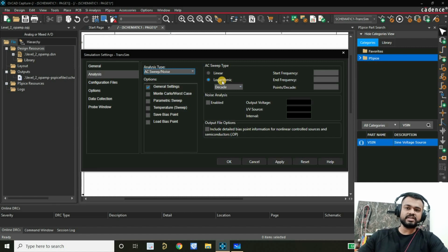First it will be the output voltage, then we'll use the dB function to convert it into decibel gain, right? So what is the formula for converting a normal gain, which is V out by V in, to decibel? That will be 20 log of gain, right? So in our case, the gain will be 20 decibel, all right? So this is something I wanted to tell you. Then we'll discuss this minus 20 dB per decade slope, and at what frequency after that it will start attenuating.